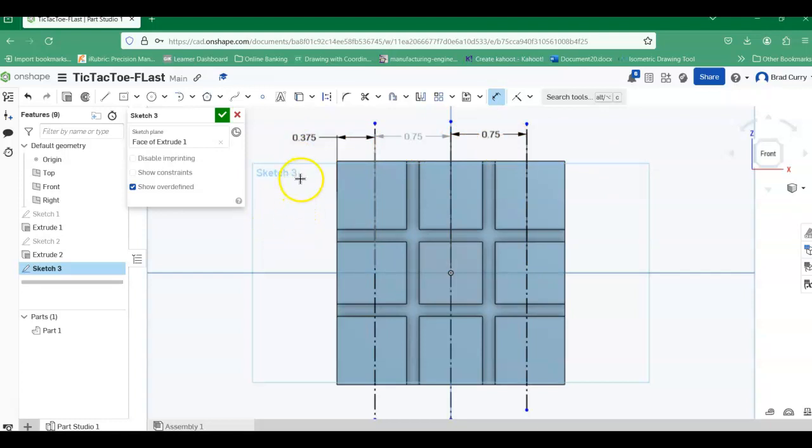All right, so that gets us into the vertical center lines or construction lines. So let's hit the escape key, get out of that. We're going to come back and we're going to create the horizontal lines right now. So I'm going to go from here over. I want to make sure that it locks into that horizontal, and left click. Again, notice, let's escape this.